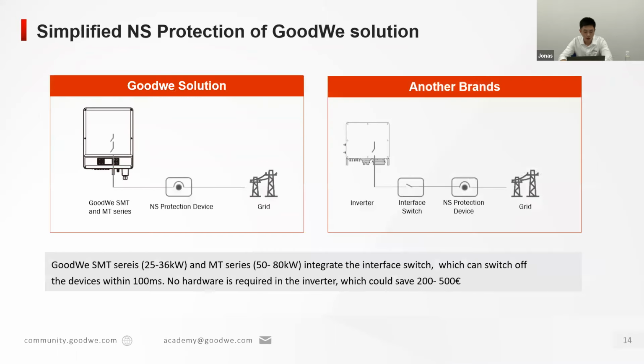To realize this function, I will say GoodWe has an advantage compared to other brands. At first, it has an inbuilt interface switch, which can switch off the devices within 100 milliseconds.